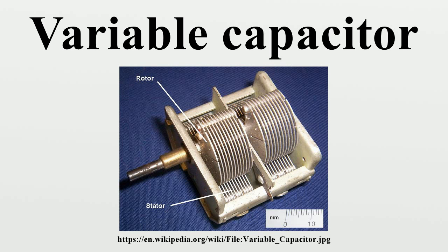Since the peak RF current normally flows from one stator to the other without going through wiper contacts, butterfly capacitors can handle large resonance RF currents, e.g., in magnetic loop antennas. In a butterfly capacitor, the stators and each half of the rotor can only cover a maximum angle of 90 degrees since there must be a position without rotor-stator overlap, corresponding to minimum capacity. Therefore a turn of only 90 degrees covers the entire capacitance range.